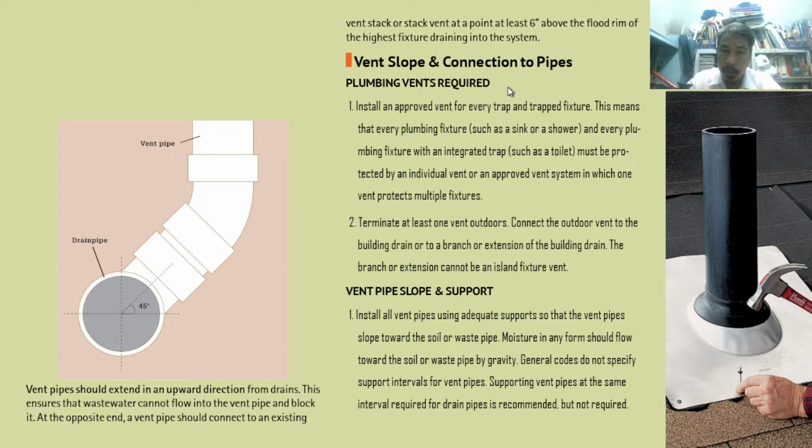How do vents connect to pipes? Plumbing vent requirements. Number 1, install an approved vent for every trap and trap fixture.